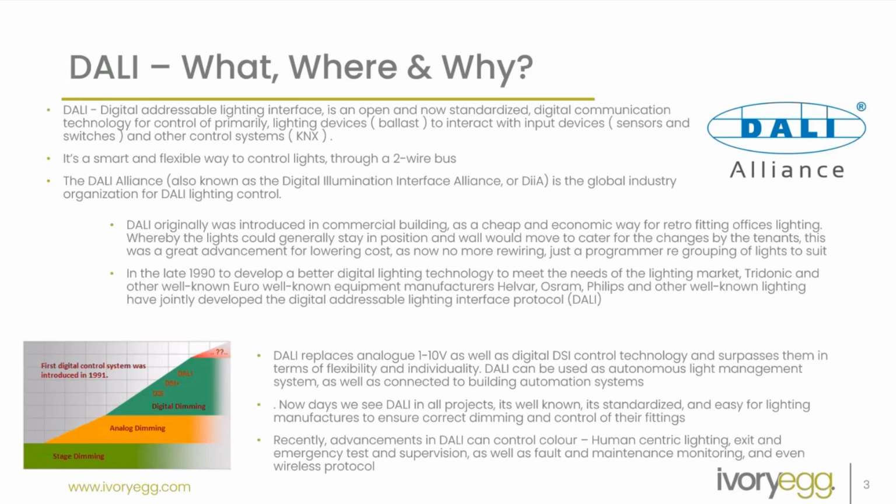What it really missed was something to keep it consistent. For those who don't know, originally with Dali, manufacturers would use the Dali protocol and change it a little bit to suit themselves. Generally you'd have to match someone's gateway with the same manufacturer's fittings. They're still talking Dali, but they've changed it a little bit to suit themselves.